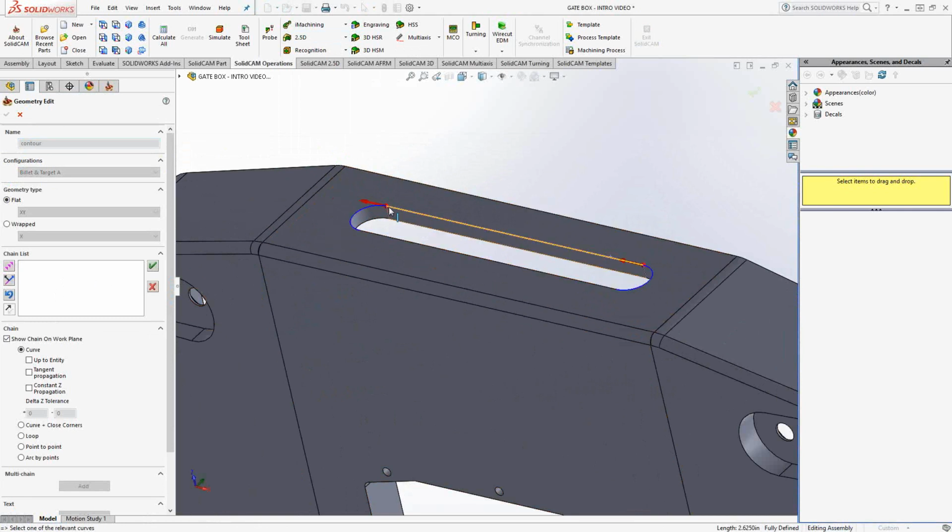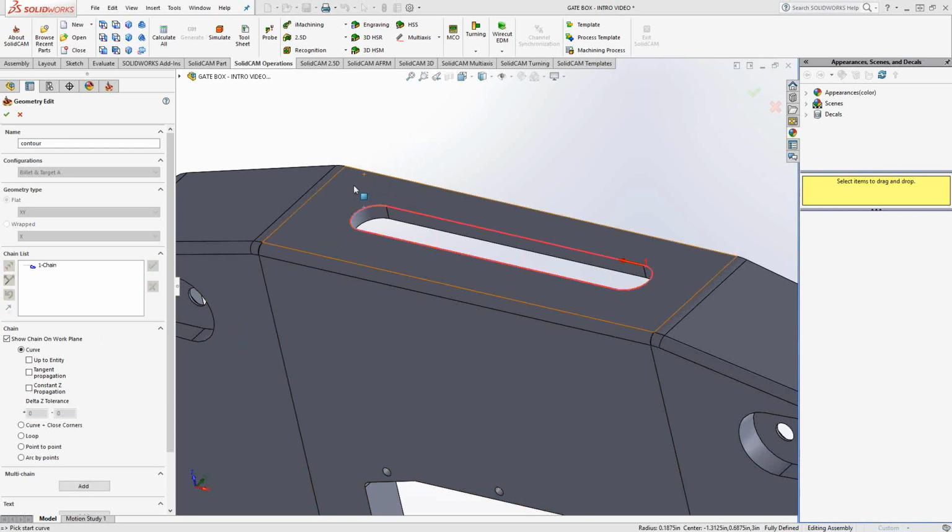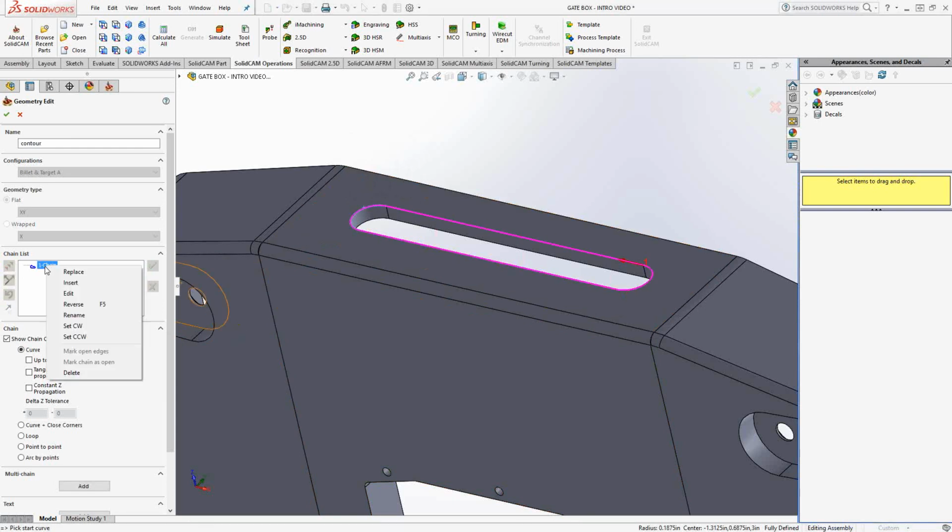In this case, I have 4 options. Either I can go in this direction, down, or change my direction and go in this direction here with this curve or that vertical line. And we could toggle through those options here. That isn't to say that I can't just choose the edge like before, but again, it just gives us an option here that if we don't want to go and individually choose small line segments or small arcs, I can just toggle through the options, and then using this function right here, just continue to add the segment as I go along to complete the chain. Now, that is if I were to do it manually.